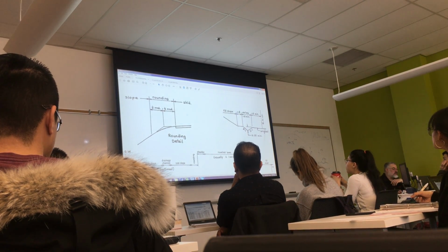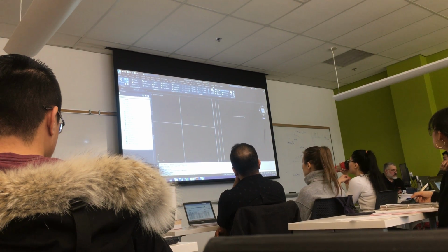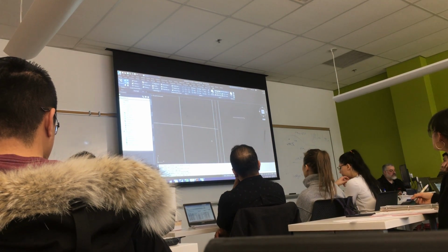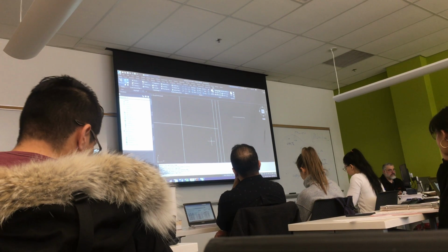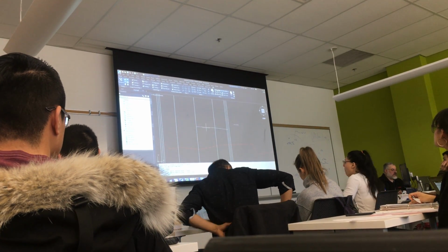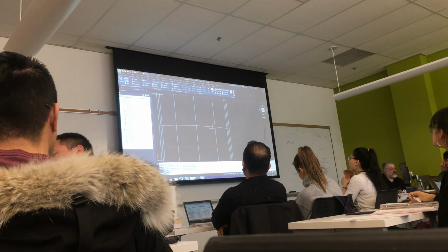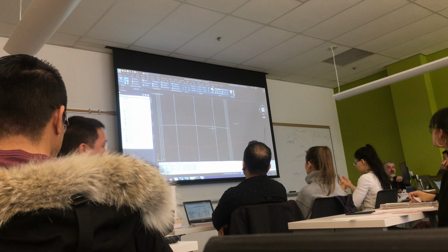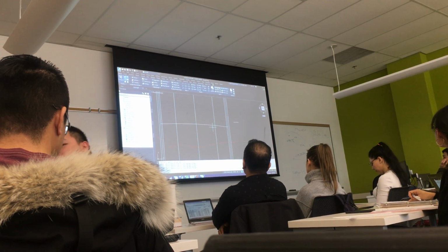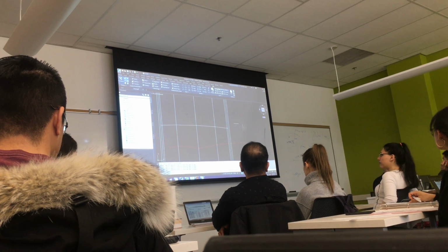That's why I established the center of the rounding. So I'm going to extend not to the shoulder, but all the way to the middle of the rounding. Okay. Everybody with me? Okay. I'm going to mirror this. It's exactly the same on the other side. Right? So this is 2%, this is 6% to the center of the round. Okay. Those are the 3 main parts of the road. The lanes, the shoulders, the rounding. Any questions so far? Okay.